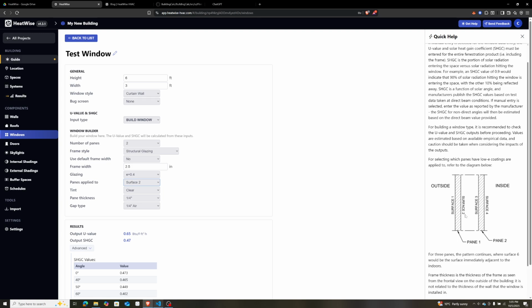So it's one of these inside surfaces, so you wouldn't put it on an outside surface because that will get scratched or damaged. It goes somewhere where it's not going to be tampered with. And having lower emissivity just means there's going to be lower radiative heat transfer between the two environments. The specific location might be hard to know, but should be published by the manufacturer. If you don't know, we recommend the Surface 2 as a best guess, but of course you want to be as accurate as you can. So we'll leave it as Surface 2 for a minute and look at our next options.